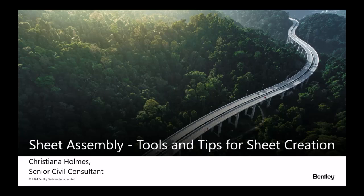And so we're going to just start off with an overview of your drawing production tools and sheet creation tools. And if you've been working in OpenRoads any number of years, then you probably have come across these at some point, but you will find all of the drawing production tools on the drawing production workflow or drawing production tabs. And so that will include all of your MicroStation labeling tools, civil labeling tools, and the ability to create sheets.